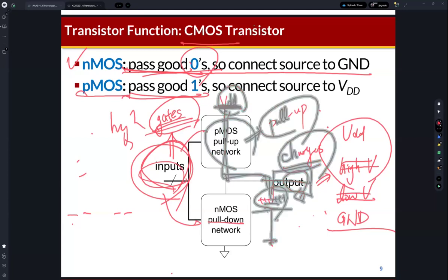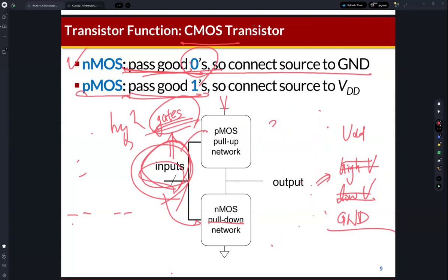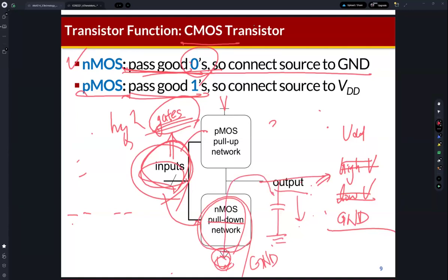So inversely, this is also a capacitor. This is the pull down network. Using the NMOS transistor, we can make the voltage level of the output low. How? You know this is the ground. Another node of the NMOS transistor is connected to the ground, and if this output node is connected to the ground, then charge is actually dissipated.